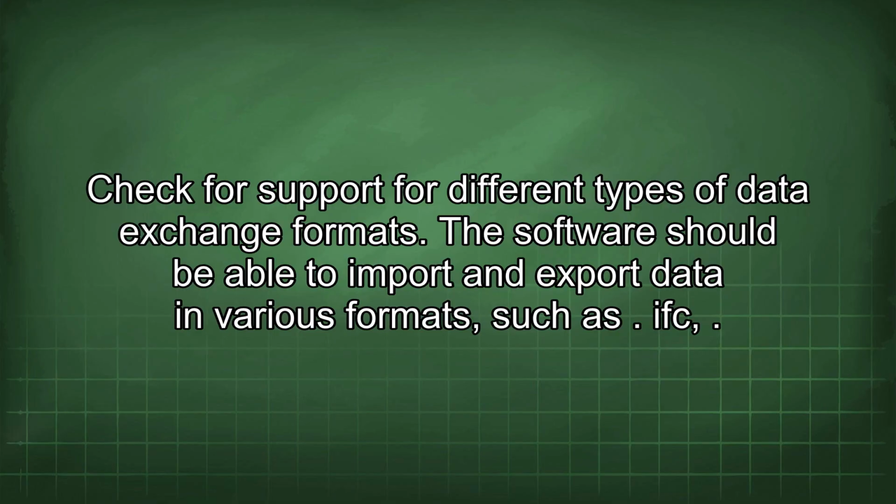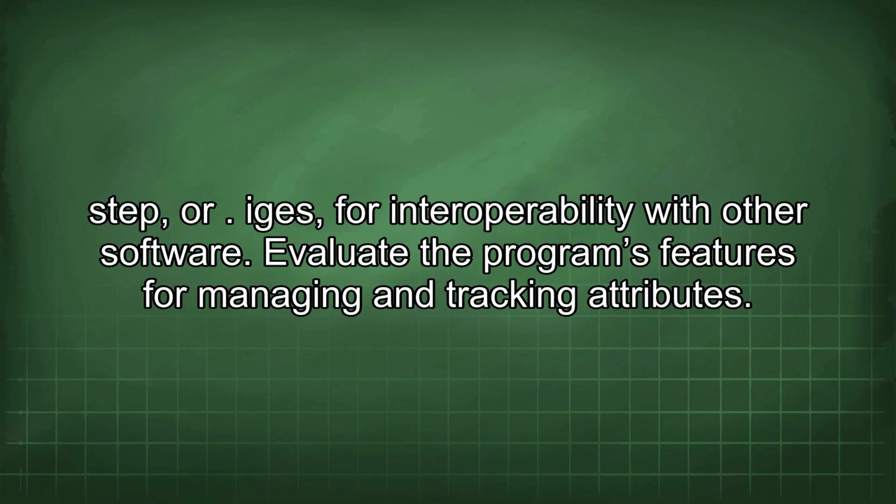Check for support for different types of data exchange formats. The software should be able to import and export data in various formats, such as IFC, STEP, or IGES for interoperability with other software. Evaluate the program's features for managing and tracking attributes.